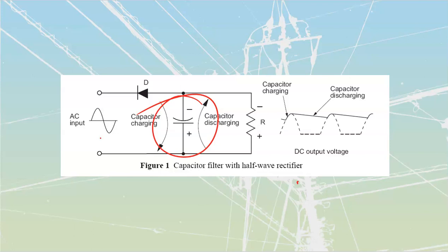In what we would do by applying it to 120 volts or whatever our system voltage would be, way too fast, and it would end up blowing up. You would have to do that slowly, that you'd strip it away and then build it on the other side so you wouldn't overheat them. But just directly reverse connecting them in, it's too fast and the thing just grenades.